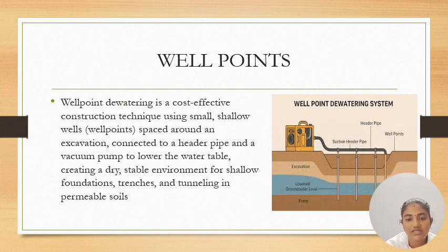And well points. Well point dewatering is a cost-effective construction technique using small, shallow wells around the excavation connected to a header pipe and a vacuum pump to lower the water table, creating a dry and stable environment for shallow foundations. That is called well points.